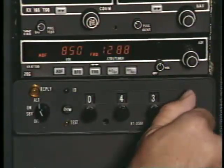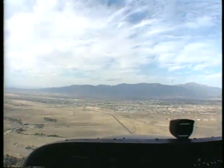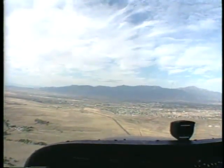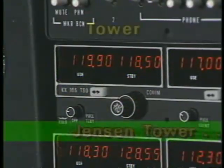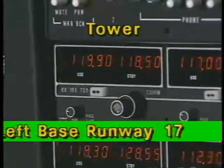In most cases, the controller will give you a transponder code and ask you to ident. "Cessna 740, radar contact, 23 miles northeast of Jensen, turn left, heading 220 for left base, runway 17." As you near the airport, approach control will let you know when or where to contact the tower. "Cessna 740, 5 miles northeast of Jensen, contact the tower 119.9." "Cessna 740, tower on 119.9." "Jensen Tower, Cessna 62740, 5 miles northeast for left base runway 17."